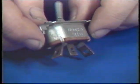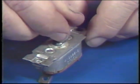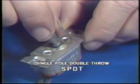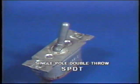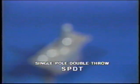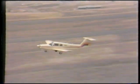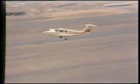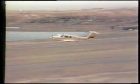A switch with three connections and either two or three positions is a single pole, double throw, or SPDT switch. This switch may be used to operate the same circuit in two different positions and is commonly found in the circuit to raise and lower aircraft landing gear. It may or may not have a neutral position.